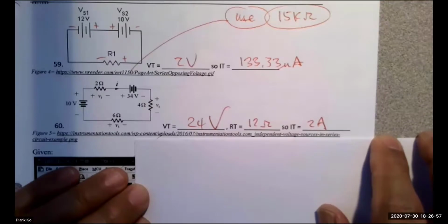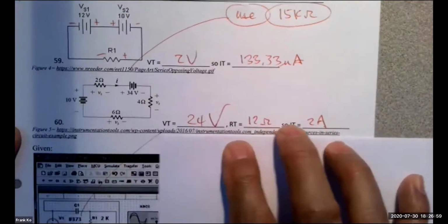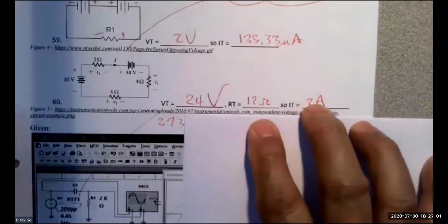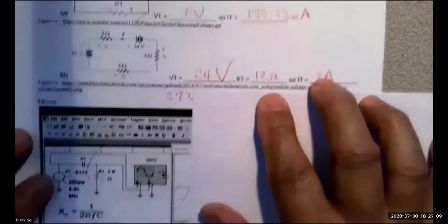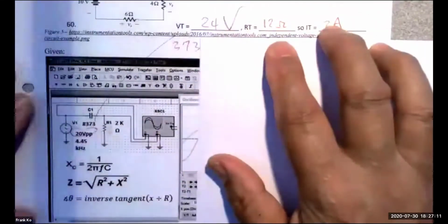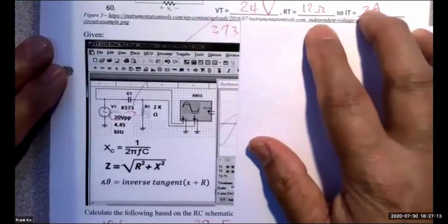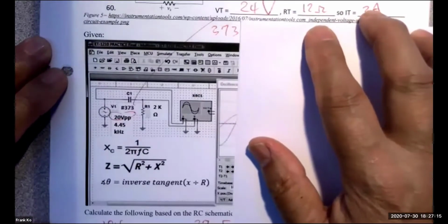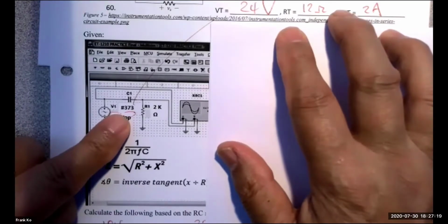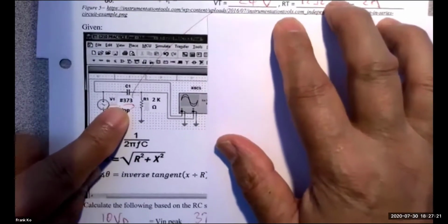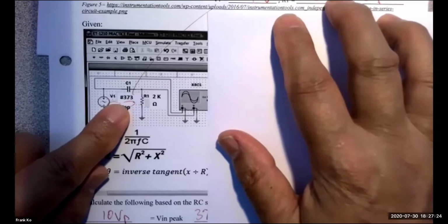Okay. Now, the next question, which you will see some variation of for sure next week, will be your phase shift. This happens to be phase shift analysis with respect to a resistor capacitor combination, and you know the code guy is not going to give you a capacitor value. The code guy is going to give you a code. What do you do with the code? You have to decode it to find the capacitor value.